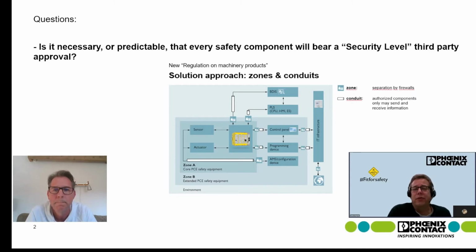That helps for the qualification, but nevertheless you have to take into account, for example, also non-safe components like bus couplers and things like that, where you have access points from the user perspective. So these components also need to be evaluated, and that was what I'm trying to explain before, on the system level later. That means you put all these components together and see where I have access points, where I have possibilities for a hacker, let's say, to attack, for example.